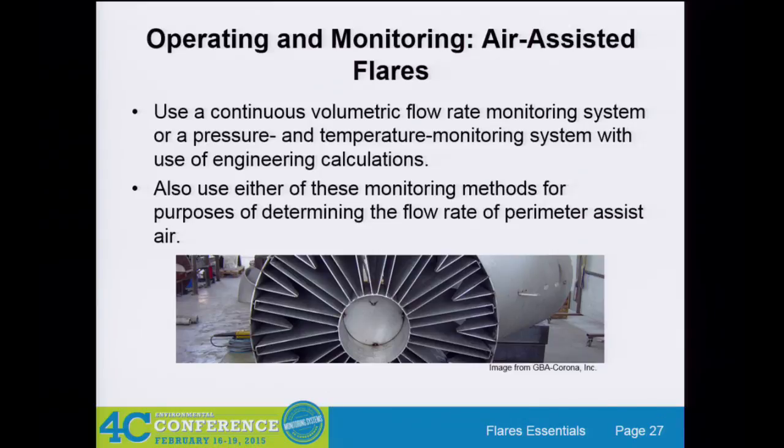And you're going to need to use a continuous volumetric flow rate system to determine the flow rates. One of the things, even with the vent gas flow rate, is they say you need to determine the volumetric flow rates. If you're going to use a mass flow meter, you then need to correct back to volumetric using the molecular weight, not the molecular weight from the flow meter, which if it's an ultrasonic you would get from it. You have to use the molecular weight from your composition analyzer. So that's another little nuance.